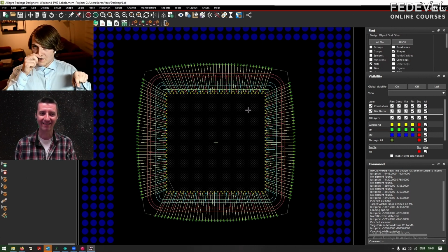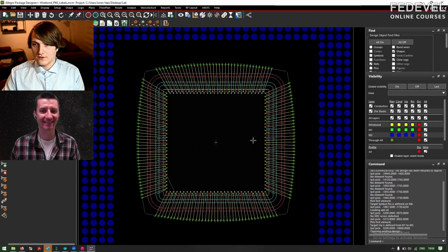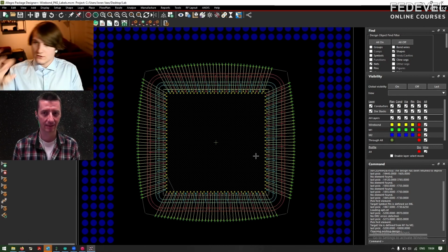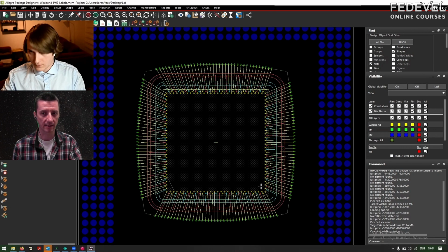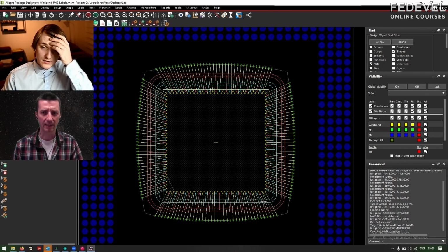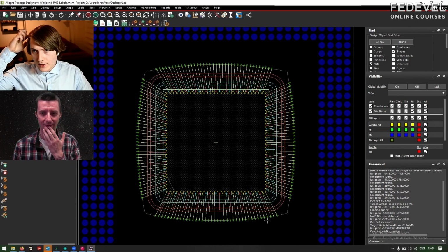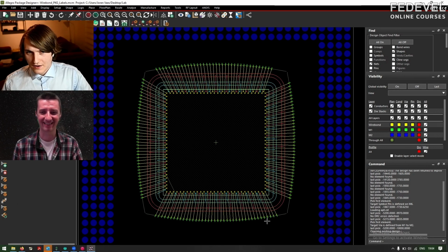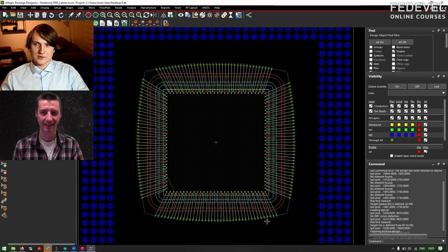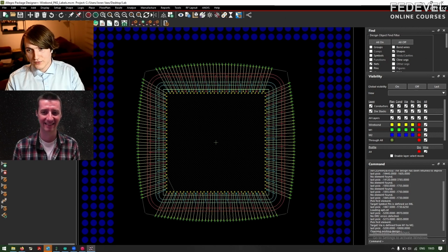Oh, I was thinking how it is actually done. So they put the silicon upside down? Yes. So that's one option. Or if you have solder balls on the silicon, then you put it with the solder balls on the package. And then it is soldered in an oven, like standard components? For example, yes. But is it done at higher temperature? Not necessarily. I would expect the silicon to come off or fall out. Not necessarily, because after the soldering, they place an underfill material. They place a glue underneath that then holds them together.